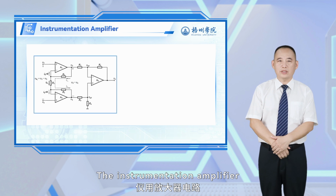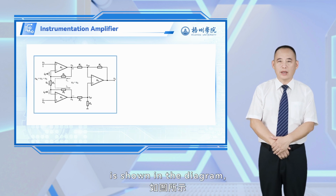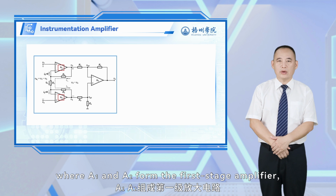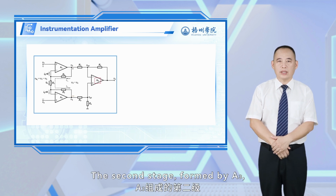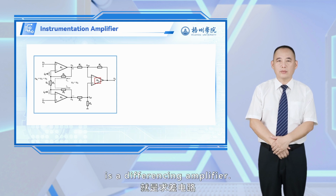The instrumentation amplifier is shown in the diagram, where A1 and A2 form the first stage amplifier, with V1 and V2 as its inputs and V3 and V4 as its outputs. The second stage, formed by A3, is a differencing amplifier.